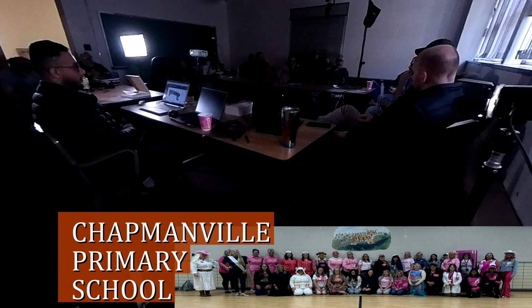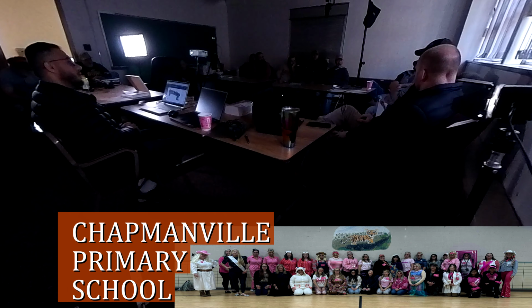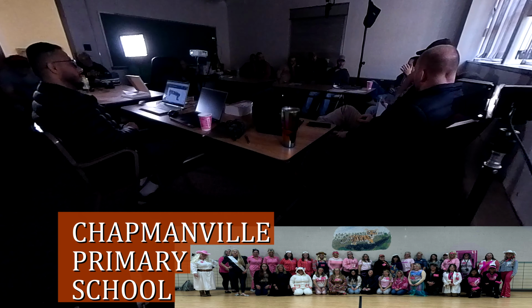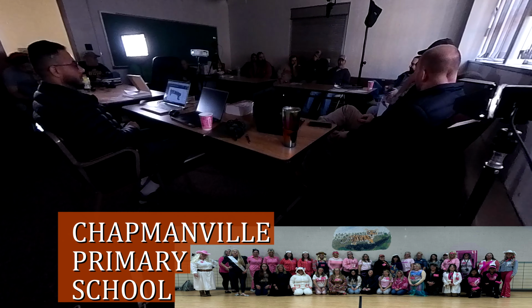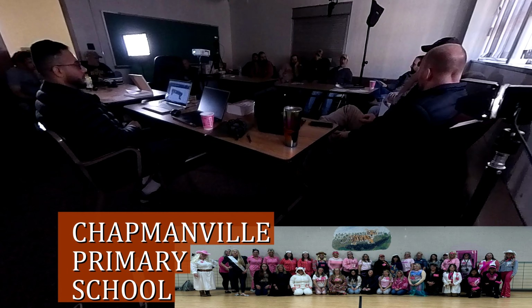One of them shut down, and all that water caused every room up there to mold. But you want your outside air damper shut because that's going to bring in moisture if you have it open. So with the outside air damper shut, if nobody's in the building, you want it as warm as possible. If there is staff, you can bring on certain areas to keep them comfortable.